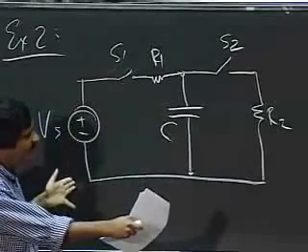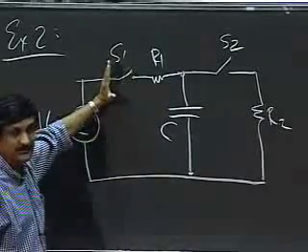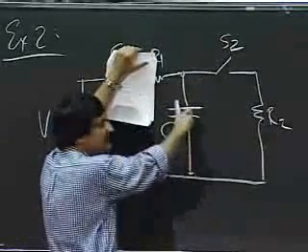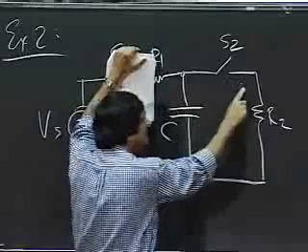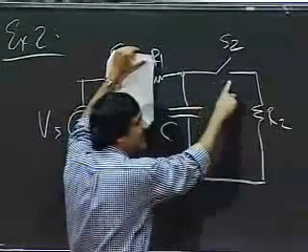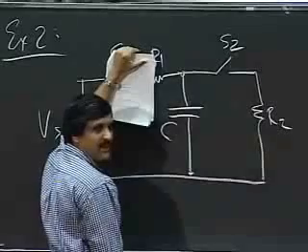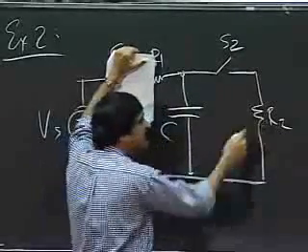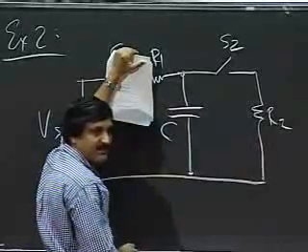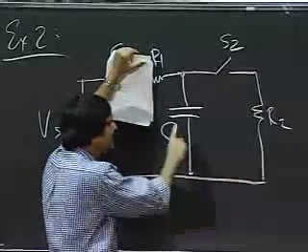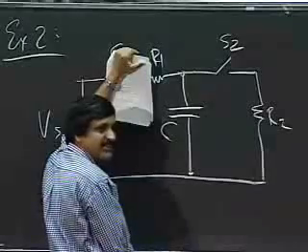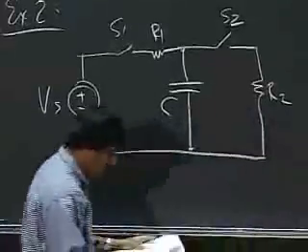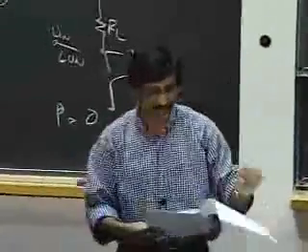That gets me to the end of T1. At the end of T1, I open this switch and close this switch. When I close this switch, I have some energy on the capacitor, and the voltage across the capacitor begins to drive a current through this resistor R2. And now the capacitor supplies its stored energy, and its stored energy then begins to dissipate through resistor R2. And if T2 is very long, then all the charge in the capacitor drains out, and the voltage on the capacitor at the end will be 0. So that's just a high-level description of what goes on.